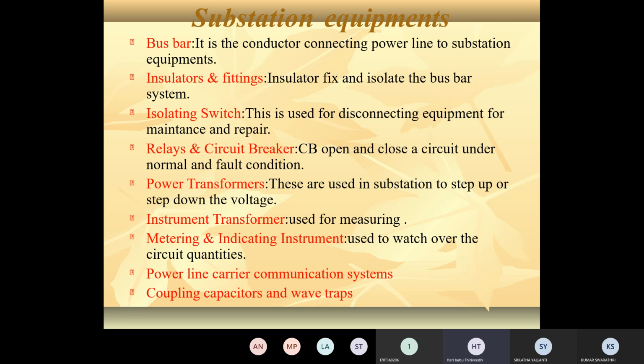The most commonly used material for insulators, as is well known, is porcelain. We know that many types of insulators exist: pin type insulator, suspension type insulator, strain type insulator, and post insulators. Generally, pin type insulators are used below 11 kV, that is, in rural areas.